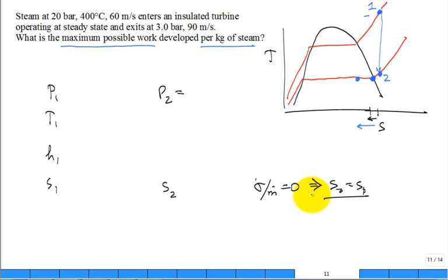It's not an isothermal expansion through the turbine. It's not an isenthalpic expansion through the turbine. A property known as entropy is constant. It's isentropic. S equals constant. It's an isentropic expansion through the turbine. So this sets S2 equal to S1, which was 7.1271 at, what, 3 bar?